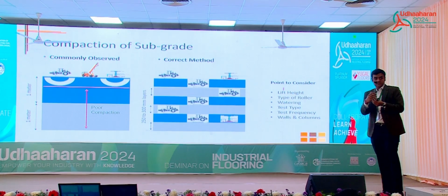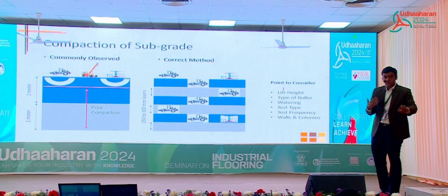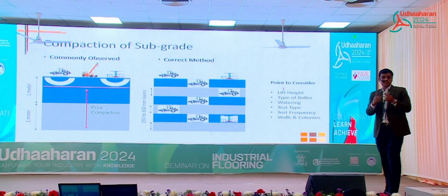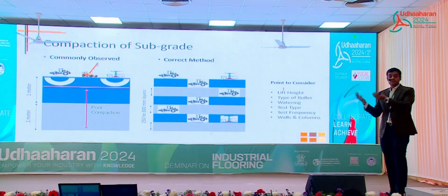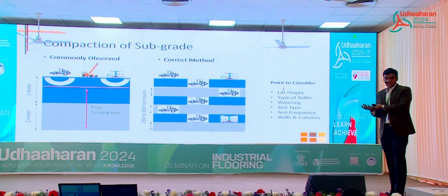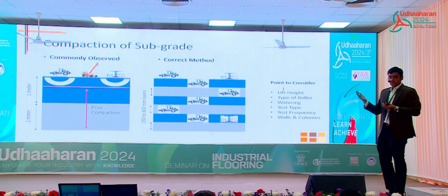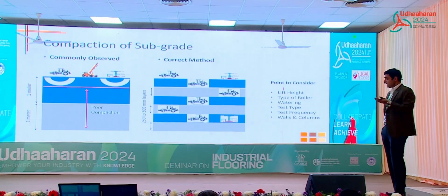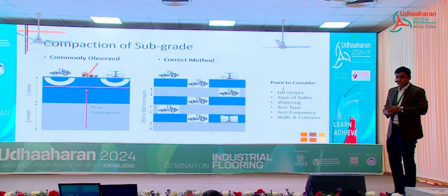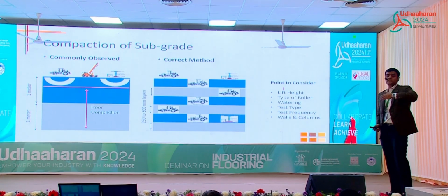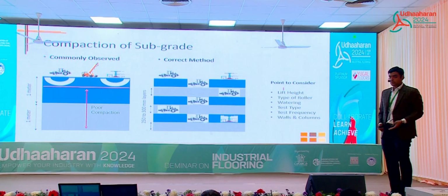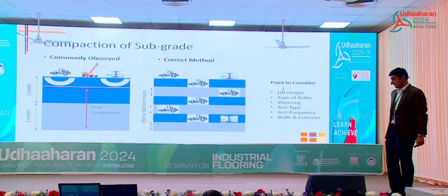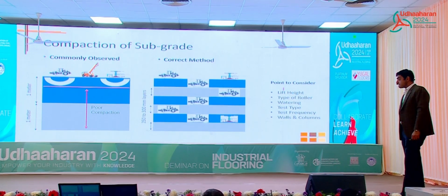Your plate load test will test maybe 300, 400, 450 mm. So this is very common, right? And all your tests are passing. But then why are you seeing settlement at site? 2 reasons, because eventually, even the guy who is rolling it knows that you just test the final layer. Nobody bothers to test when you're kind of lifting the layers. And the final layer is bound to pass, but then your earthwork is bound to fail because of these reasons.